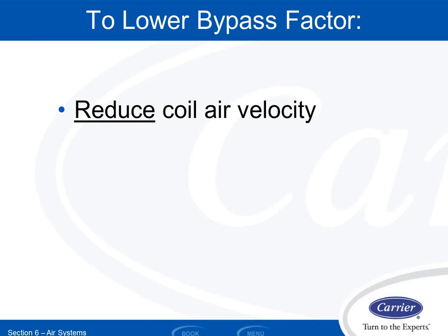This is very often seen on residential systems. Anything that has an ECM or variable speed motor from a furnace standpoint typically has a dehumidification terminal on the furnace, and when we energize a dehumidification terminal from a dehumidistat, it tells that furnace, hey, put on cooling at the lowest stages possible. But this time, run the blower as slow as we possibly can, because I want to really, really dehumidify and not do too much sensible cooling and really do my work on the latent side. So reducing the air velocity is one way to do it.